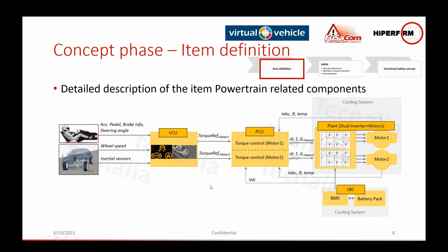The main item, as I said, is the vehicle control unit. This is the main ECU where it controls the vehicle dynamics, the inputs from the acceleration, deceleration, and so on. And it's calculating as well. It's introducing not just the in-wheel motors, it's as well the different functionalities that we could have in this new kind of powertrain setup. And one of those is this torque vectoring. And here as well it will be really important in the validation phase to analyze the impact of this torque vectoring on this powertrain.